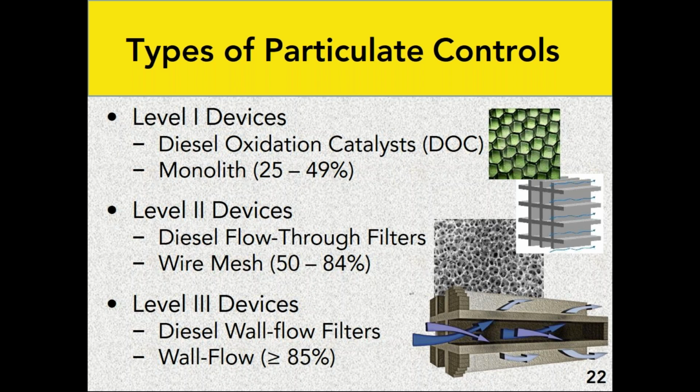Anything solid is going to get trapped inside those holes. So what happens is the exhaust gases go into the open channels with the particulate matter. The gases themselves pass through the sidewalls and go out the other end of the device, while the particulate matter cannot, and it can't go through the plug at the end, so it gets trapped inside the chamber. That does create a problem because ultimately that will collect to the point where the soot overwhelms the ability of the filter to collect anymore.